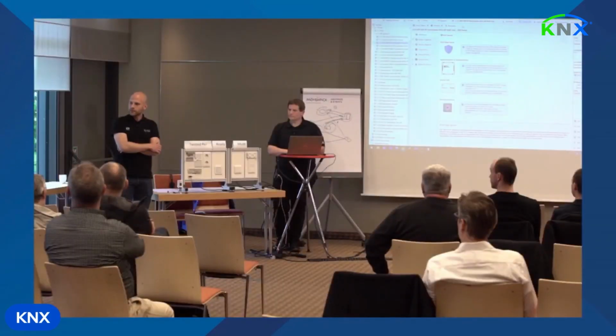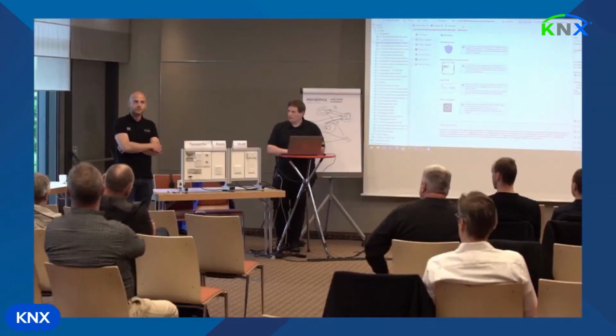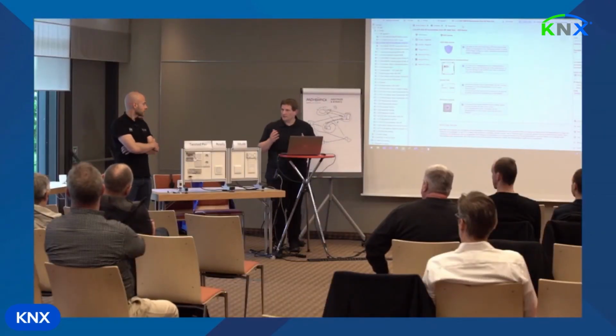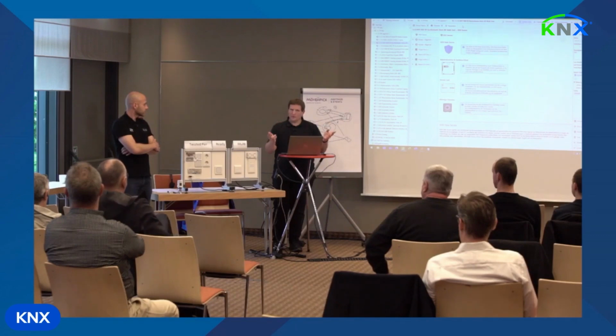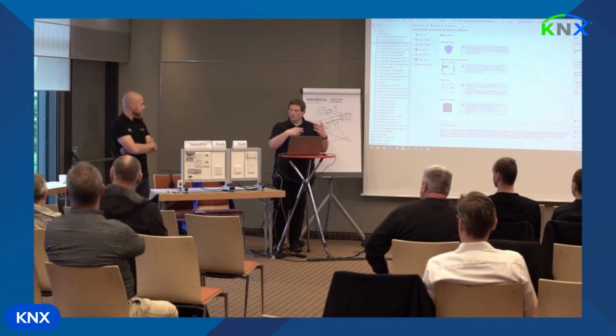Thank you. And then one more question to the RF guys, which is, can you have more than one domain in the same system? Yes, and you should. Like I earlier said, if you have a large installation, it's better to have independent media couplers opening up independent domains instead of trying to have only one media coupler and use repeaters to reach devices which are too far away.